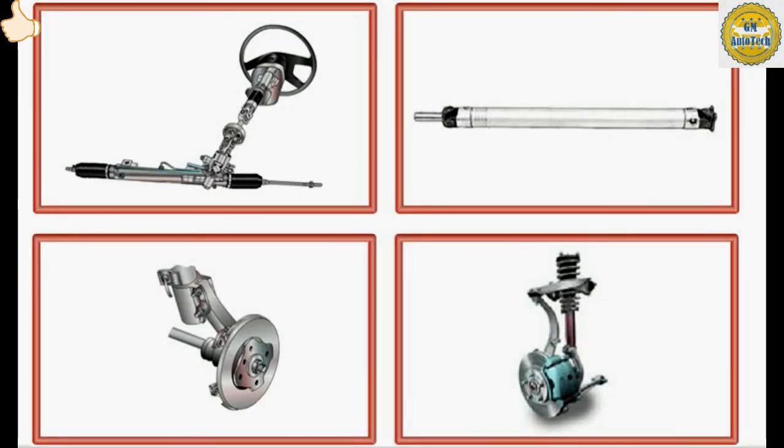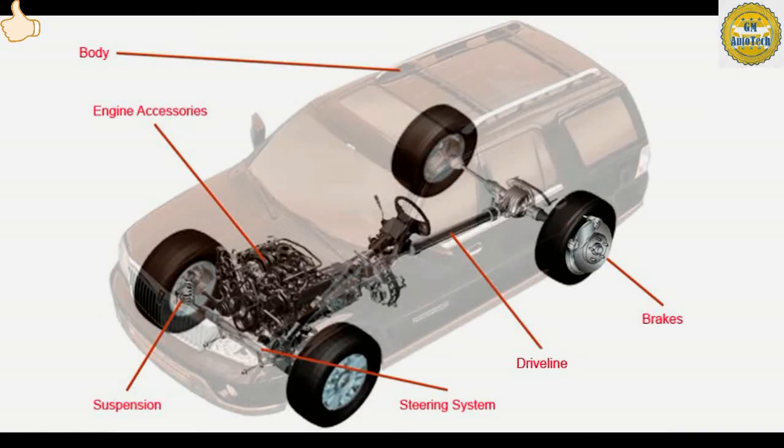This topic covers other types of noises that we don't think of as being related to vibration concerns. These noises include the momentary pops and clunks associated with worn or damaged components, the grinding noise associated with gear-driven components, and wind noise or air leaks. Many times these concerns are identified with a visual inspection. Now our graphic depicts the components or systems that could be responsible for causing noises. The graphic includes the vehicle's body, steering system, suspension, brakes, driveline, and engine accessories.